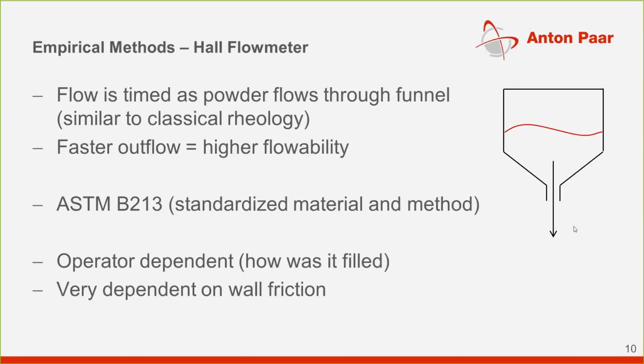What is a bit of an issue here is that this method is dependent on the operator, so how it was filled, because if this powder is more pre-compacted, it will flow differently out of the funnel. As well, a very strong influence, which is measured here, is actually the wall friction between the powder and the funnel wall.